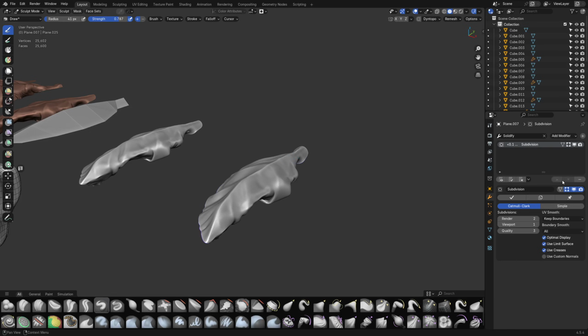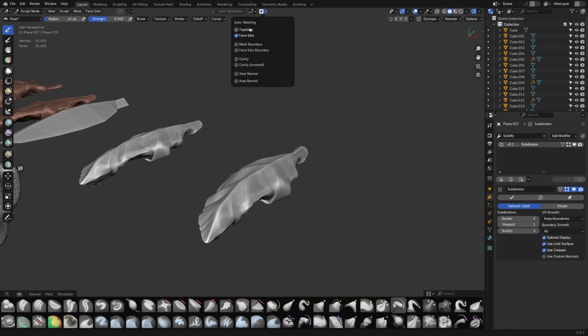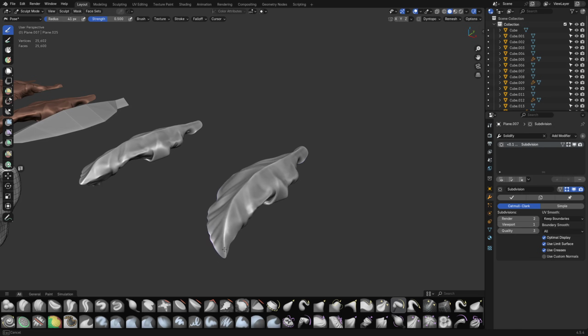When you're in sculpt mode and you have a subdivision, turn use deform only on. It will turn the subdivision off while you're sculpting, but you could probably try to get away with doing some big deformations now using the pose tool and other things like that. So you see if I limit by face set, it's only going to do the one face set. But if I do all of it, we can start to bend it around.